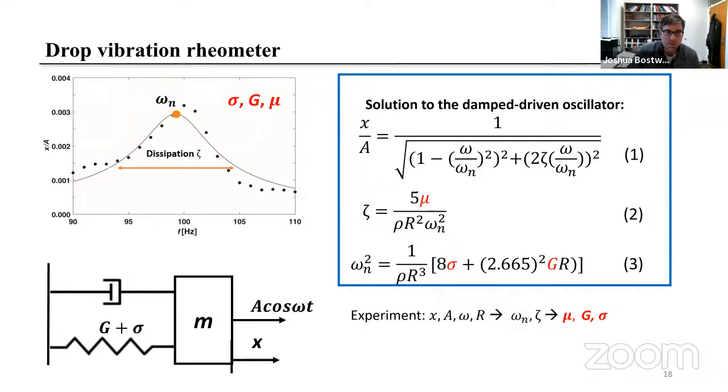So our technique is pretty simple. Like I said previously, we measure the frequency response of the gel drop oscillation, and we get these nicely sharp peaked frequency response curves with the corresponding bandwidth. What we do is apply a simple lumped parameter model. For a drop, there are a few basic physics involved. One is that the drop has an inertia associated with the motion of the fluid.